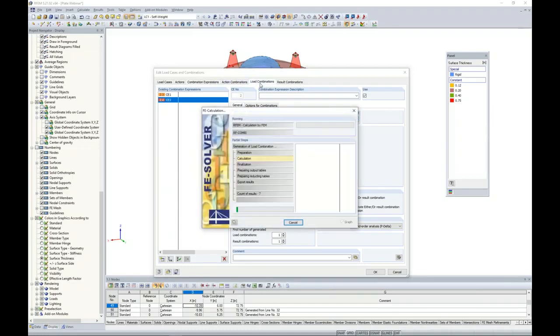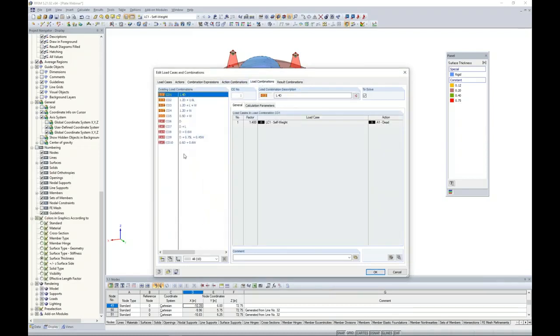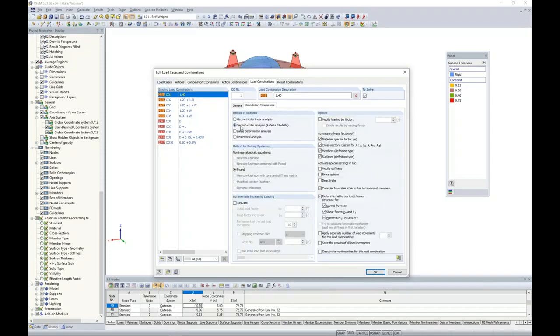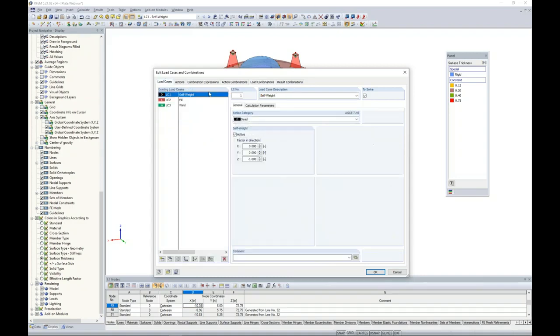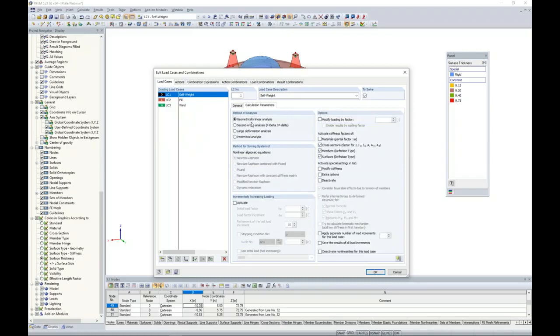The load combinations tab is going to list out all of the load combinations individually. So I'm going to see here my LRFD load combinations in orange, my ASD in red, based only on those load cases that I've defined. Keep in mind that with load combinations, the default method of analysis is second order. So we will consider both big P delta and little p delta. This is in contrast to load cases, which is run according to a geometrically linear analysis. This has to be done in order to combine it into load combinations and run according to a second order analysis.